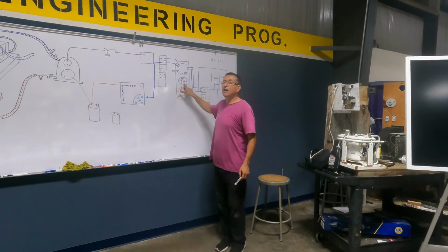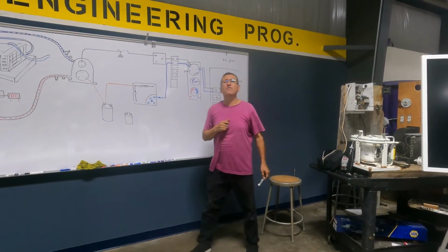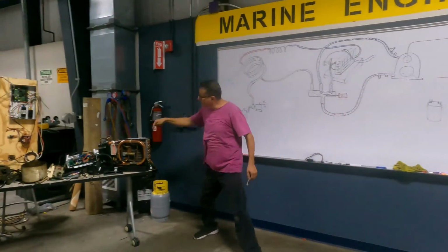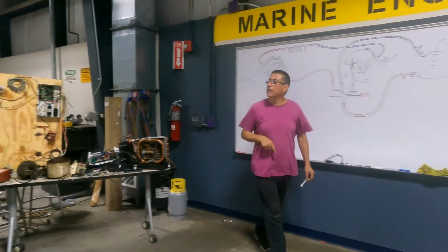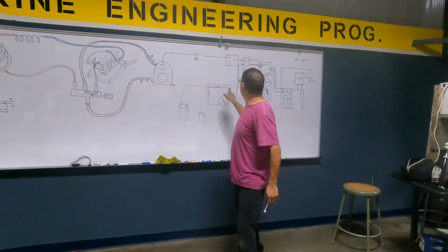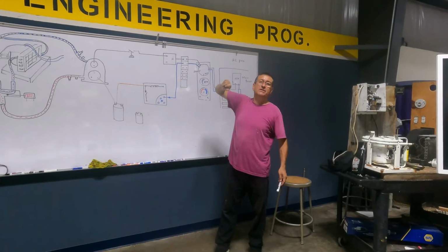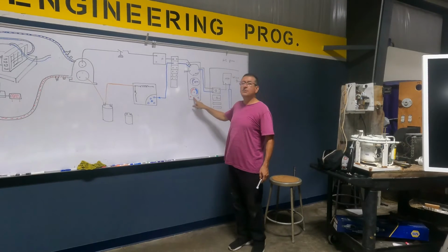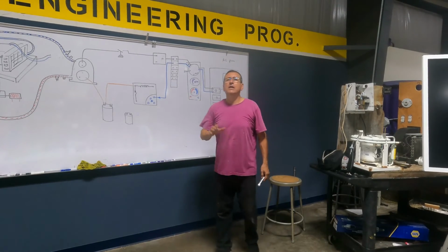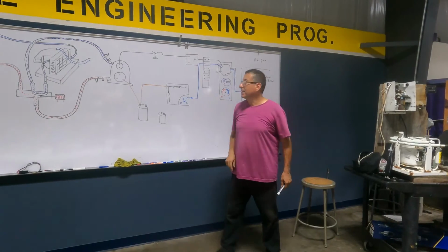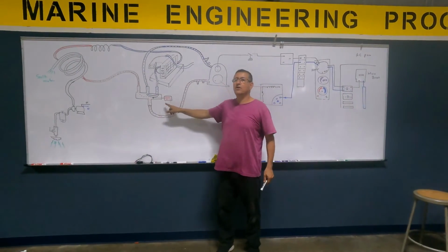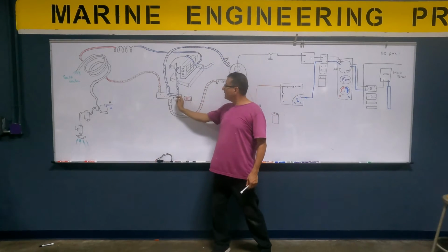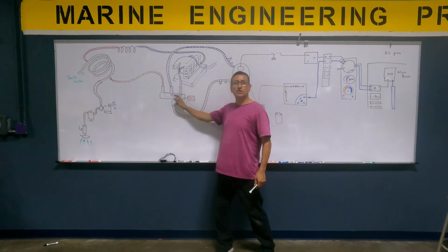Okay, after that, you have an RPM control. RPM of what? Fan. Of this fan. The RPM of this fan. Okay? And basically, this is a potentiometer. Like the volume, no? More volume, less volume, the potentiometer. And this one is a selector for heating or cooling. It's a selector for this valve, for the Y valve. This is to send the power here and activate this position or this position.